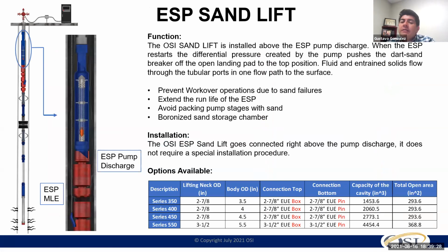So there are different types of sand and ways that sand can affect the system. On occasions, and I'm giving you a wellbore on the left, so we can go from the top down, you're dealing with a lot of sand. What we're giving you here is the option that we discussed. Either we have the cup packer, so perforations are underneath it, fluid passes around, goes through my sand control method, flows up, exits around the ESP, and goes through my pump, now able to deal with that sand.